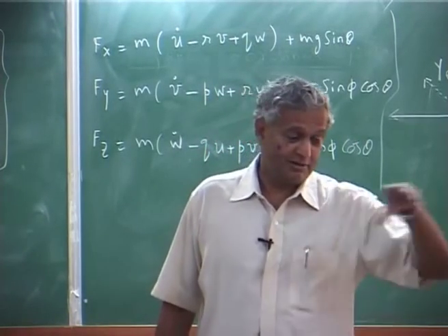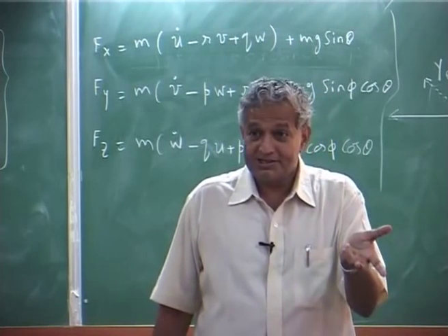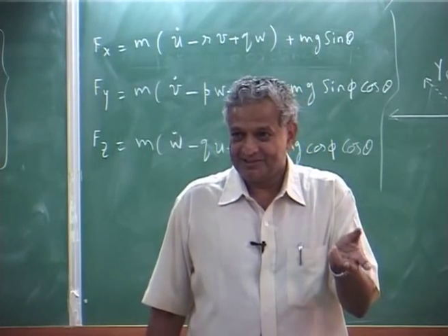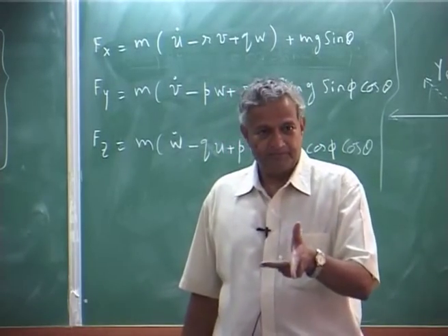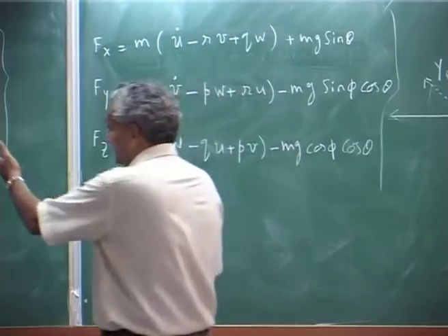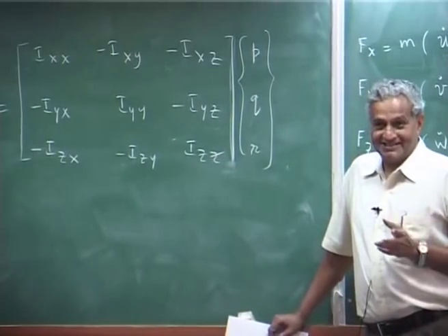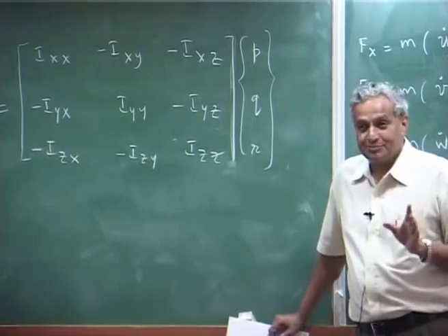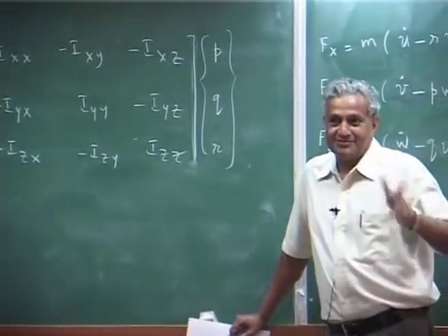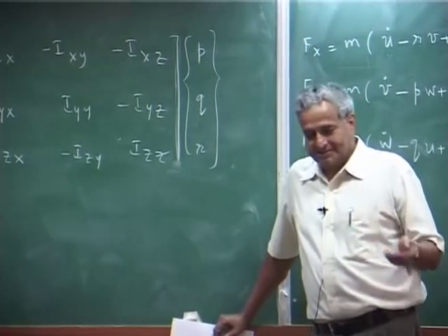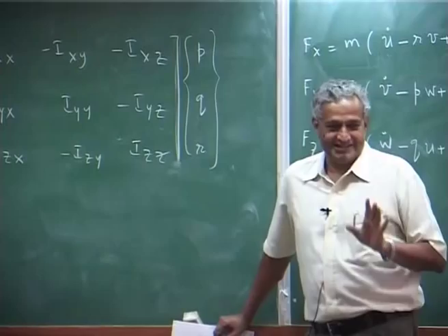Now, imagine if you put some equipment, your inertia will change. That is the reason for using a body fixed axis system, only to simplify the moment equation, otherwise it will become really messy, because these quantities do not change in the body fixed system. Of course, if fuel is expended, it changes, but you do not bother about that.